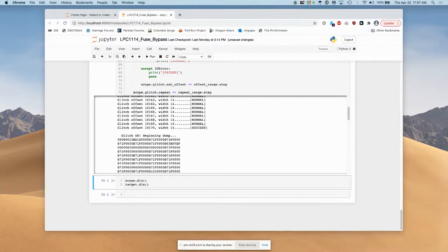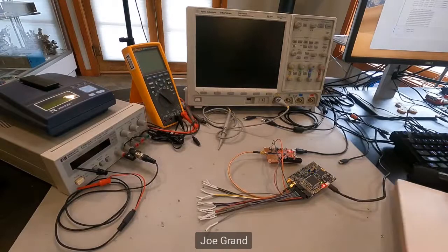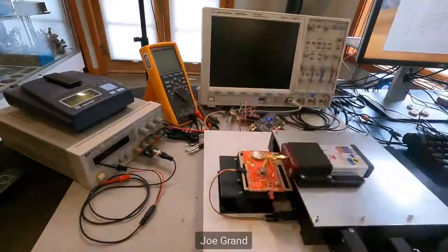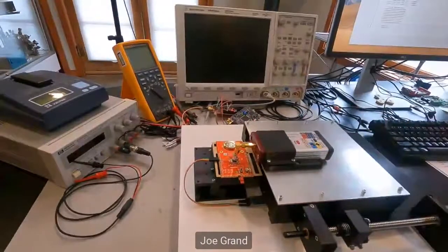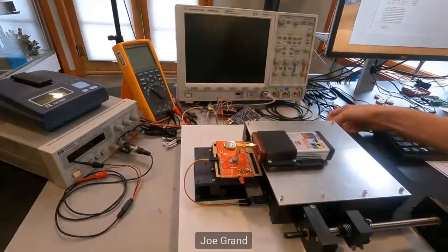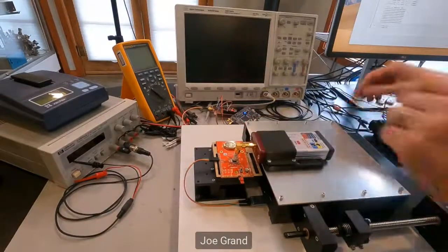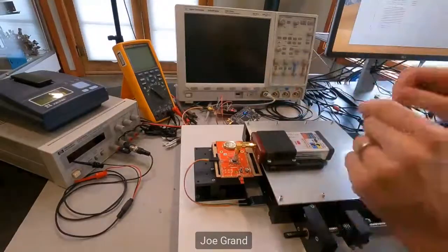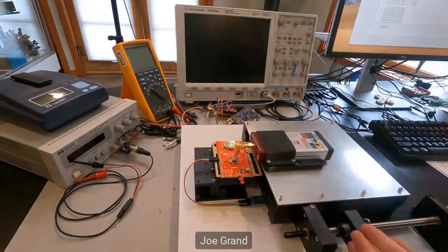The other example I do have, the last one, is the electromagnetic fault injection, which looks like this. Colin O'Flynn made a device called the ChipSHOUTER, which is really heavy. Another device that lets you do this fault injection, and you need to have very precise control and movement of the system. And this is a contactless way of doing fault injection. So you don't need to wire stuff up or modify the target board at all. You can just blast it with electromagnetic interference at certain points on the chip and cause the same sort of behaviors.